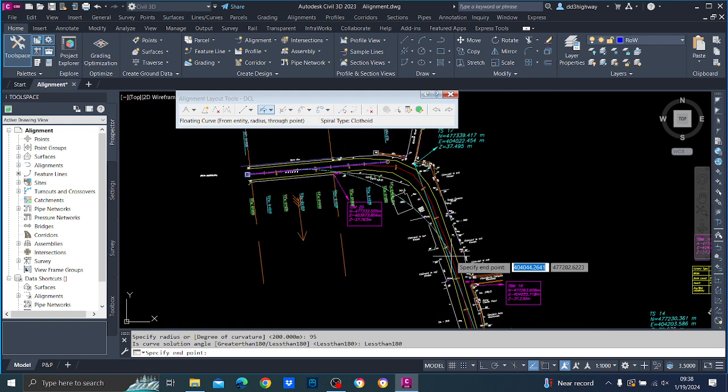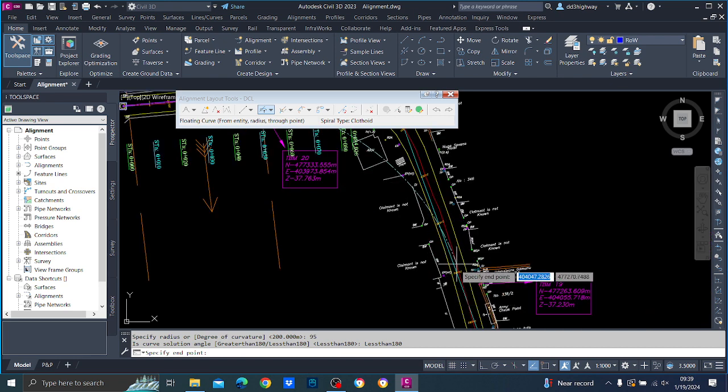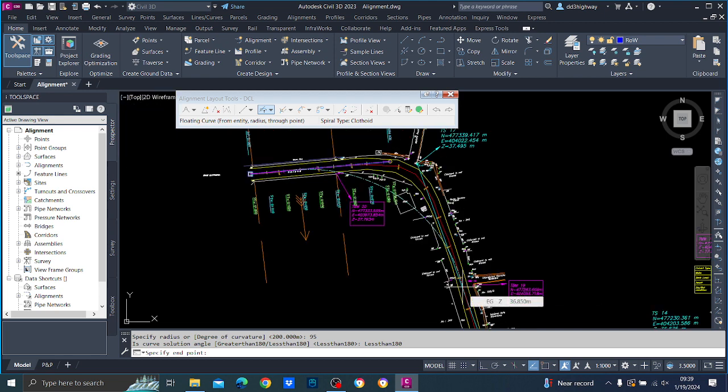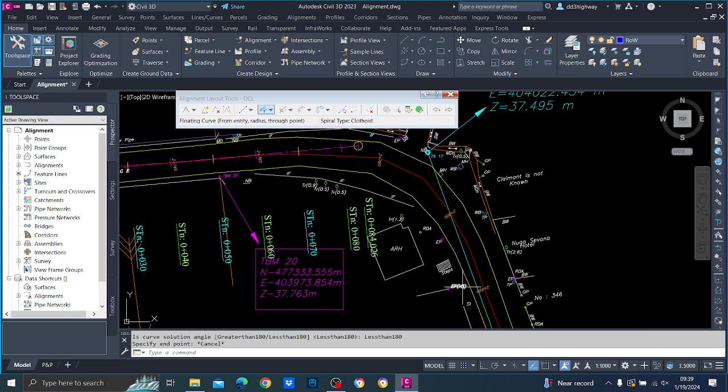You see that they are trying to draw it this way, but you have to match it with the existing road, right? So this is how it is coming. Is this possible? It's not possible because it is coming almost to the mid of the bridge. So here you will have to reduce your speed and go for a lesser design. Okay, so press escape, it's gone.